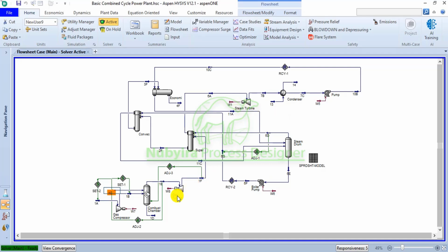So we have two turbines, a gas turbine and a steam turbine that are interconnected, you understand? The gas turbine produces 64.67 megawatts of power, and the steam turbine produces 7.125 megawatts. And you have a compressor that is using 57.06. So you subtract this from this, and you get the net power. Let me just run you through the process before I start the main body of this video tutorial.